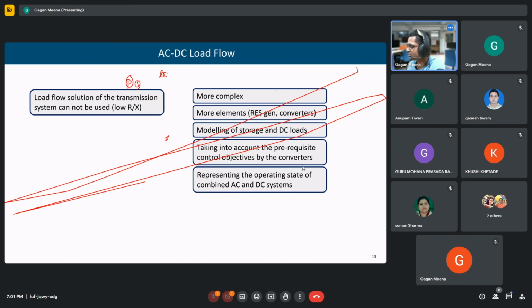we cannot assume this. Because in a transmission system, we aggregate the entire load of, let's say, an entire state. One bus is, let's say, one city. So the aggregate P demand is almost constant on a daily basis, or at least for a few slots it doesn't change much. So on an aggregation basis, such an assumption is valid.